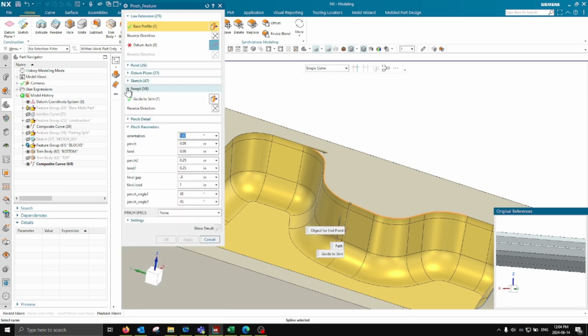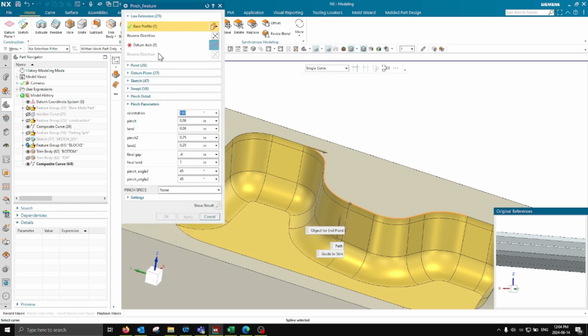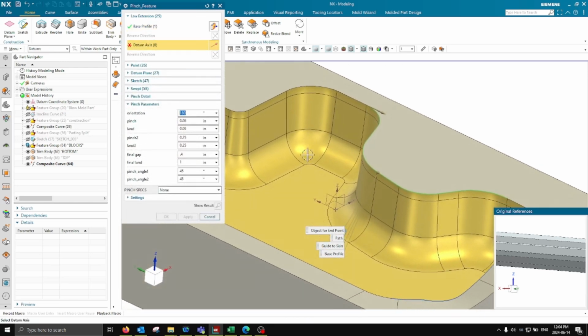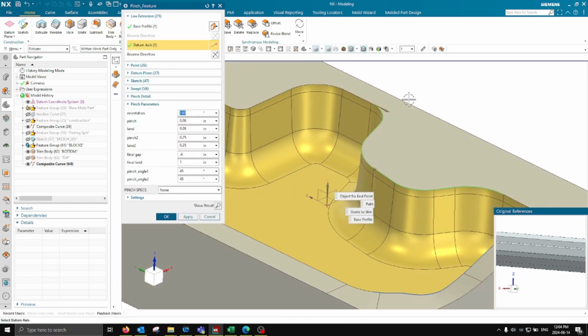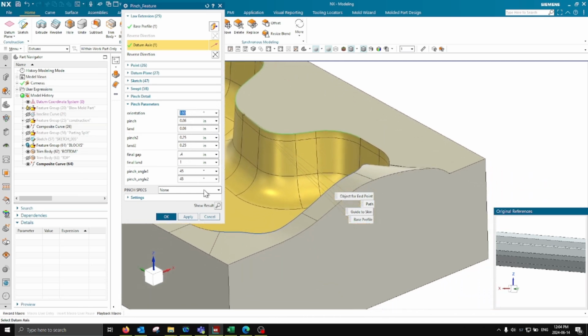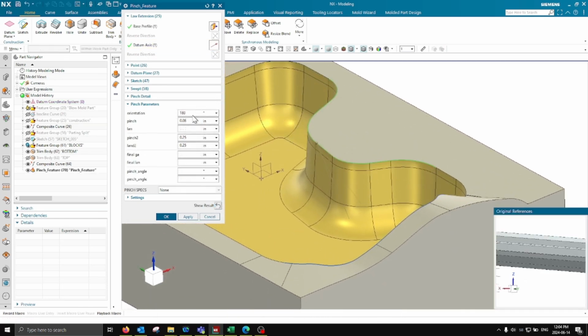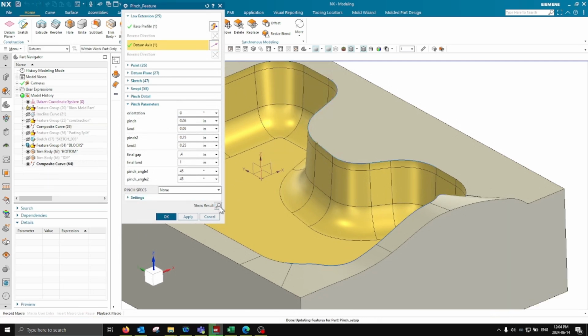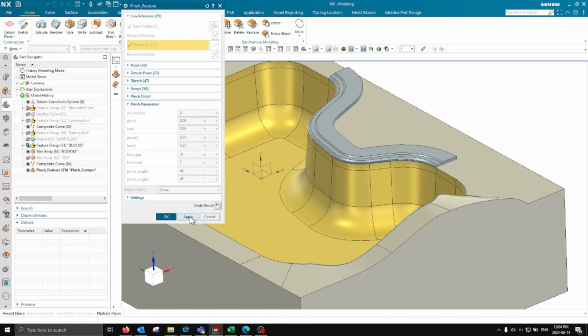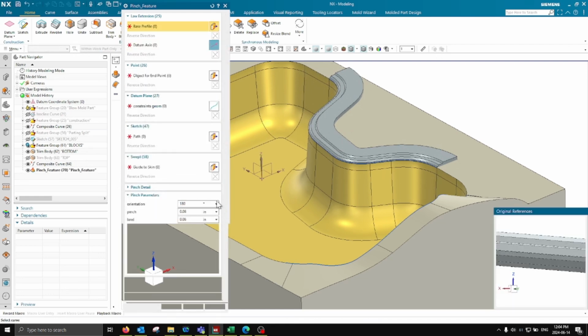So I can just close these up for now because we're not interested in those. But I do have to define the z-axis here because that's what's controlling my flat orientation of the sketch. So in this case, I'll just preview, and it's on the wrong side of the curve, so I can just switch that here to a different orientation. And we could do this with checkboxes and things, but so there's the control, there's the pinch it's going to make. I can apply that.